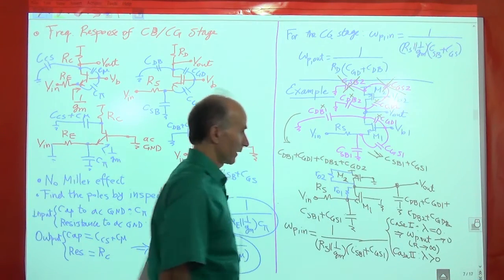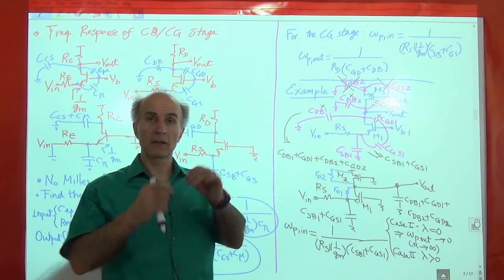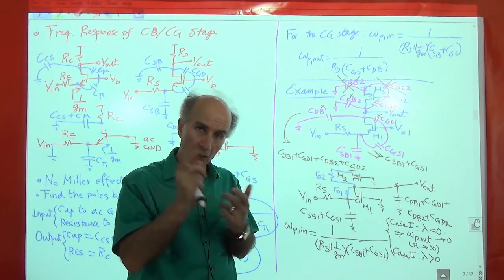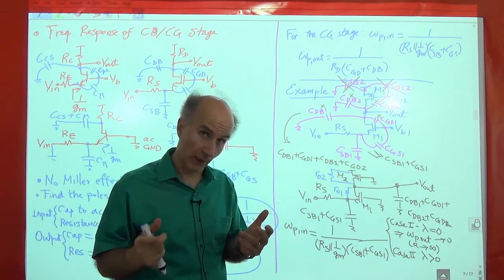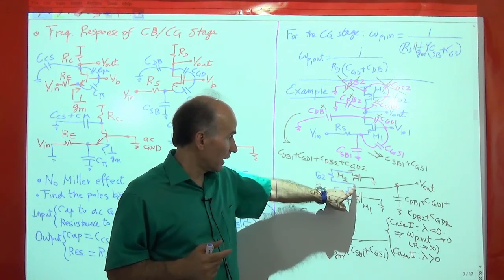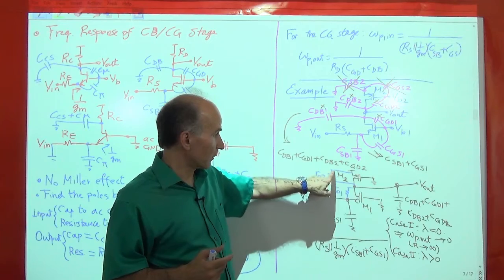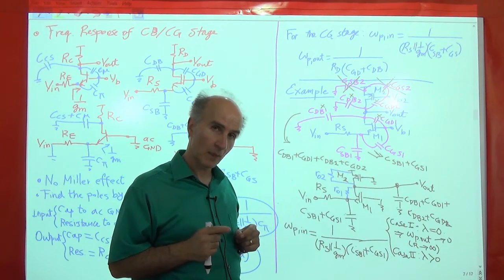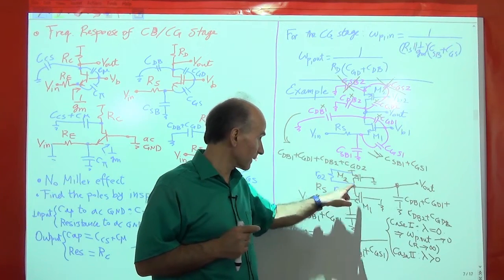Okay, all right, so then I'm trying to find the resistance that I see if I sit at the output node and look in all directions to AC ground. All right, let's sit here and look up. What we see is RO2 to AC ground. That's great, so we have RO2. But then what happens if I sit here and look down?